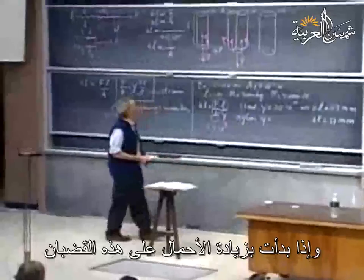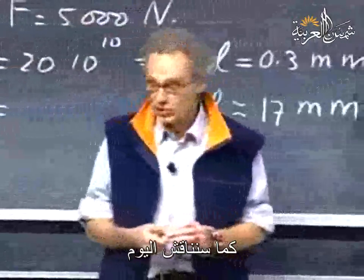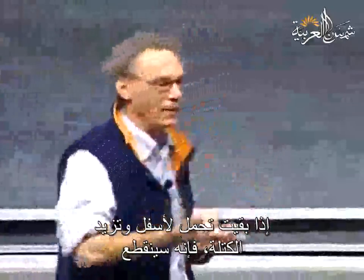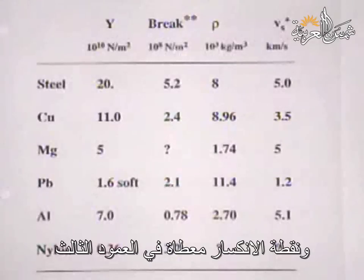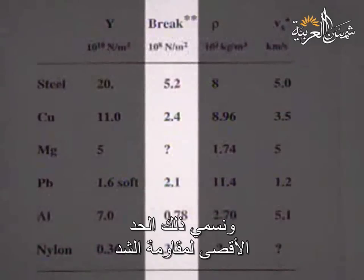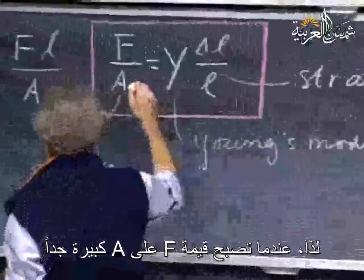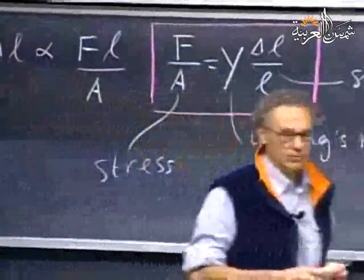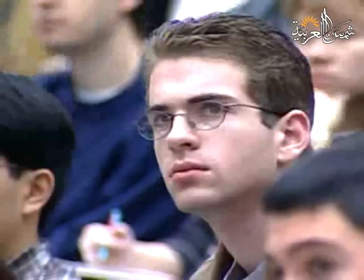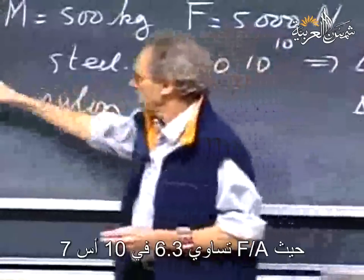If I start adding more weight on these bars, then very interesting things are going to happen, as we will discuss today. One thing which is obvious that will ultimately happen if you keep loading down, keep adding mass, it will break. And the breaking point is given there in the 3rd column, and we call that the ultimate tensile strength. So when F over A becomes too large, then it will simply break.